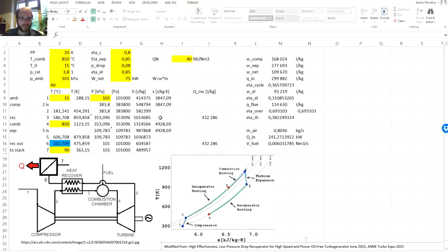In order to get the entropy in all the remaining points, it's best to use the pressure and enthalpy, as these are always two independent thermodynamic variables which can be used, for example, regardless of the fluid state, in case there would be wet steam and etc.